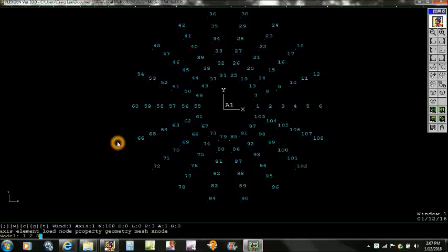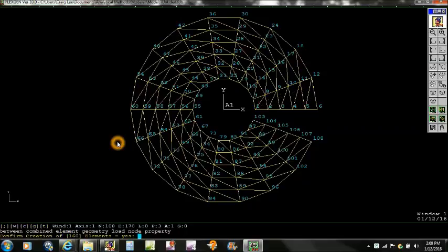Now we start creating the elements. We put our first one right there, our second one right there, and then we'll copy those elements 1 and 2, and we'll do that 4 times and go out radially, node increments of 1, and there we have created our 10 elements. Now we're going to copy those 10 elements and do an increment of 16 around the cylinder. Plate 3s, node increment this time is going to be 6, and we create our 160 elements there.